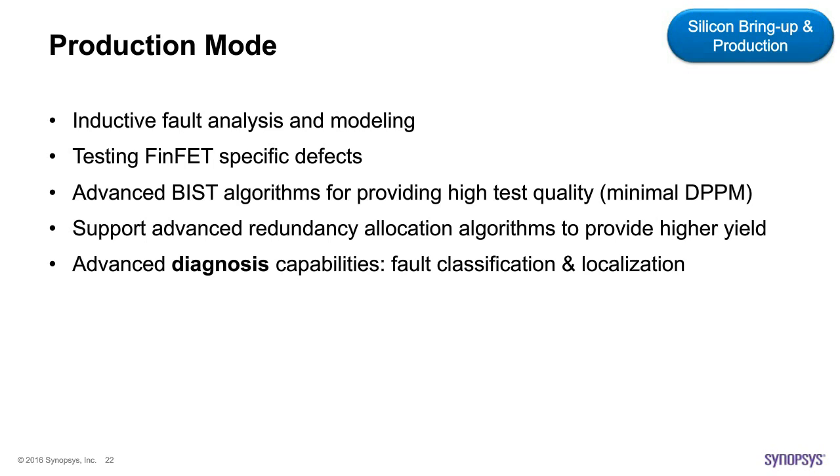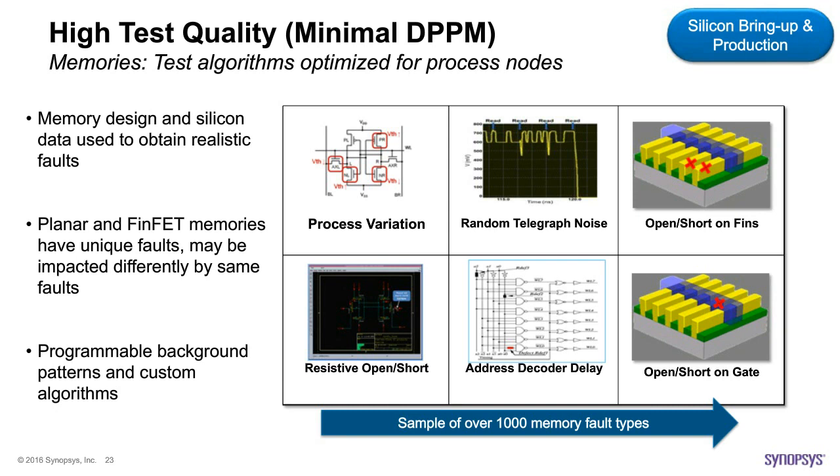Same, while we're doing that, we need to take care of the yield. We need to take care of the diagnostics as well to understand what kind of failures are happening, to locate them, to classify them, and so on. So to understand the defectivity, this analysis is important for various types of failures. And we have extended that recently to contain all the FinFET-oriented failures as well.